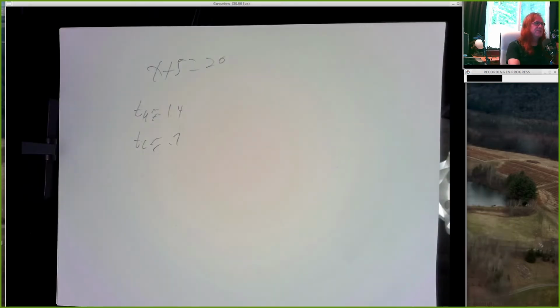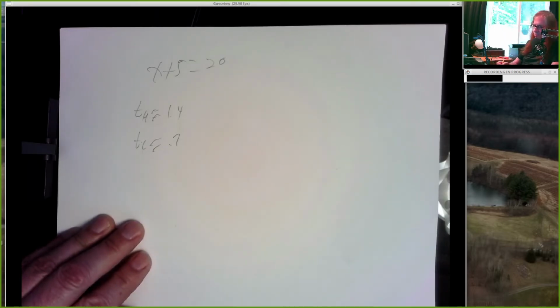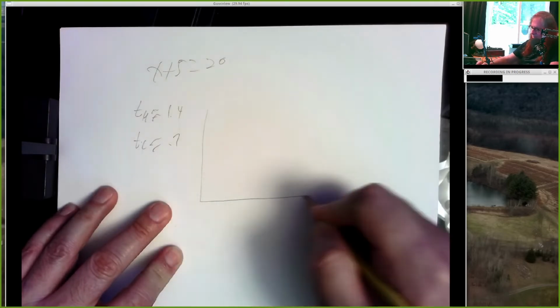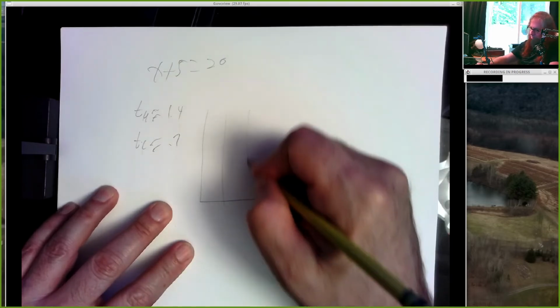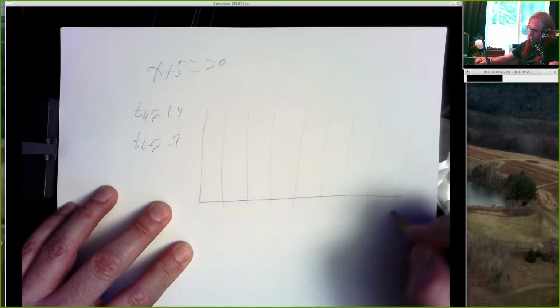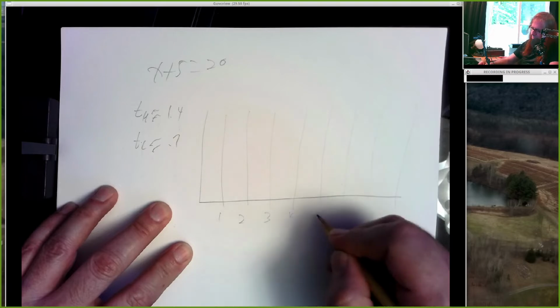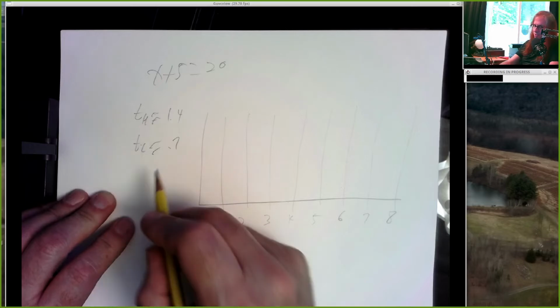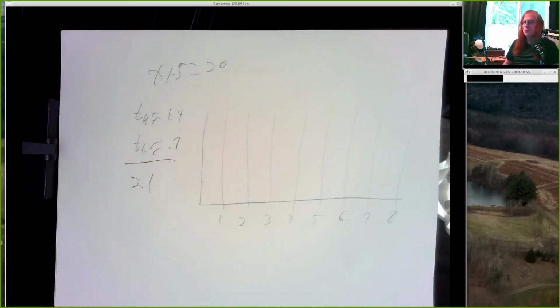So I wouldn't approximate those in your lab. I would actually plug in 0.693 times 2 for the high and for the low. But that's ballpark what the output should look like. And so if you wanted to draw a theoretical version of this, I could put seconds down here. Now if it's high for 1.4 and it's low for 0.7, the total period is about 2.1 seconds. So just about 2 seconds.